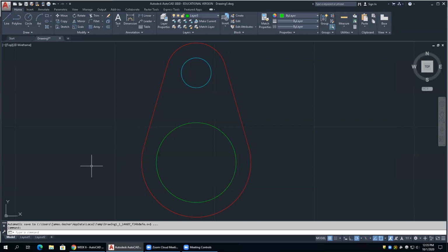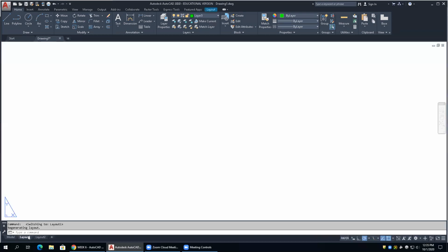So we're now going to go either to Layout tab 1 or Layout tab 2. Doesn't matter. You should see a completely blank white screen like mine. Does anybody see something other than that? You clicked on it before you were supposed to. So you've got a viewport there. Just click on the viewport, and hit the delete key. Anybody else? You need to go to the layout tab. There you go. Oh, okay. You go to the layout tab.